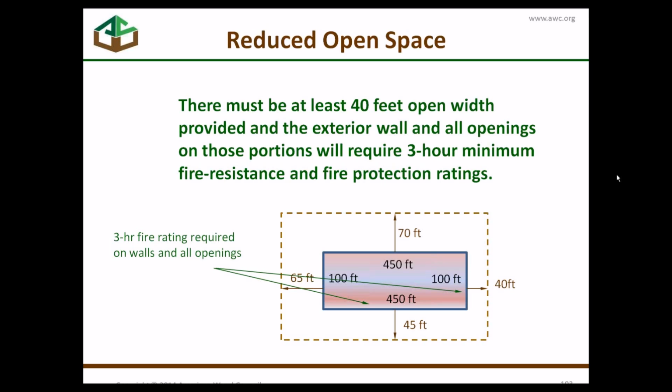Okay. Yeah, for whoever asked the question, if you take a look in the code at 506.2.1, there is an exception that allows that value of W to be increased if you're between 30 and 60 feet, and you would otherwise comply with the requirements for an unlimited area building. So there's some attempt in the code to give you more. As for the reason why, I'm just not sure. They had to make the cutoff somewhere.